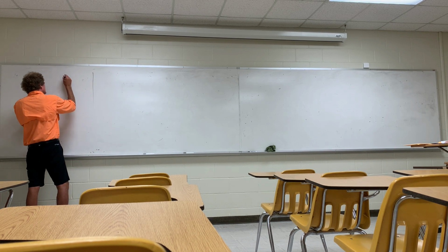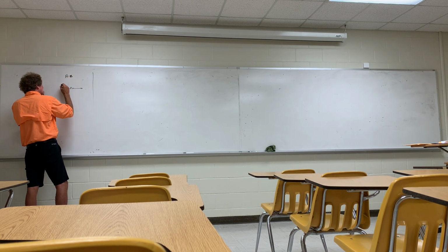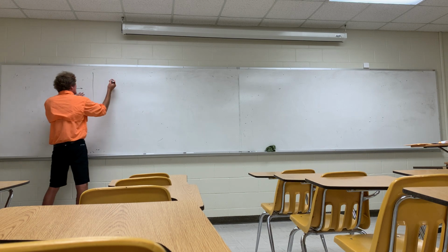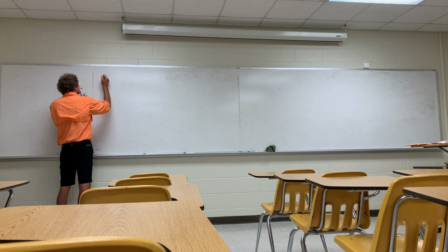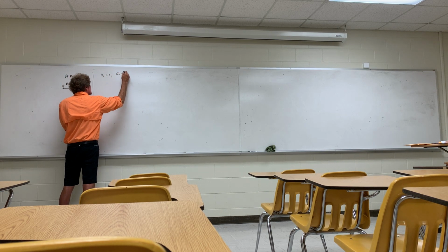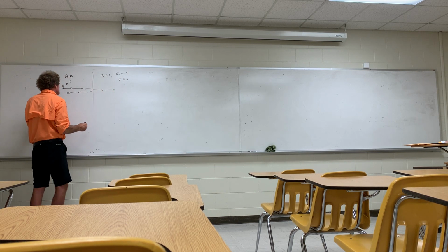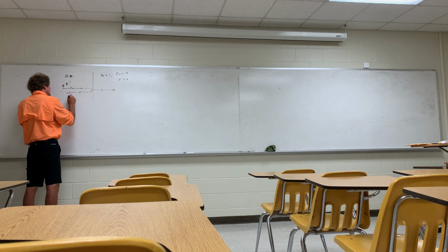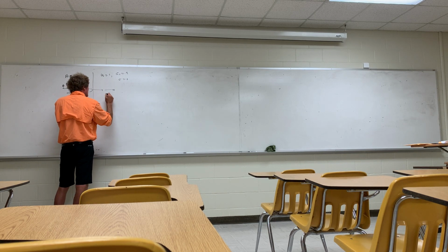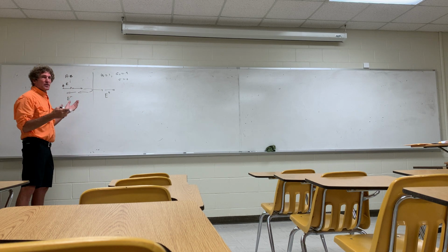I have air here, and I have a wave propagating in this direction, EI coming in. And I have a material, the only difference between that is mu relative is equal to 1, but epsilon relative is equal to 4, and sigma is 0 in this material. Wave hits, some of it's reflected, some of it's transmitted. So we get E reflected and E transmitted. And we want to go ahead and analyze this.